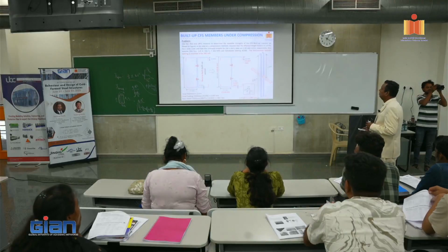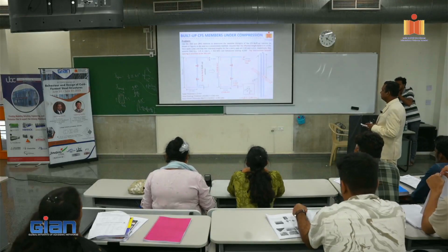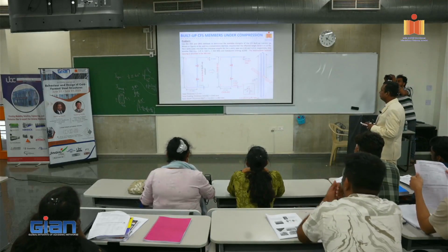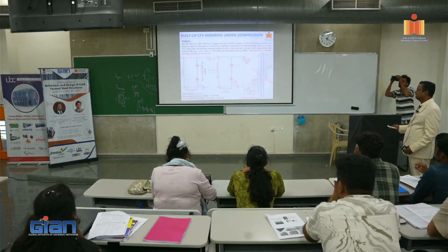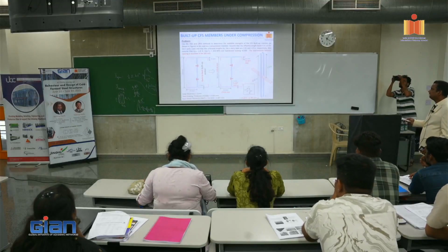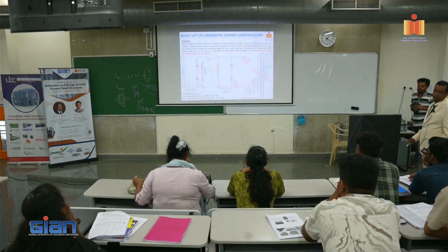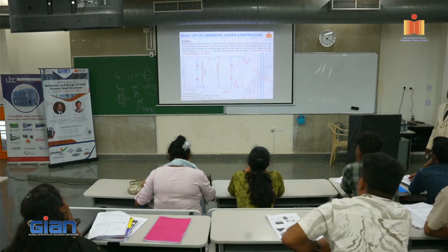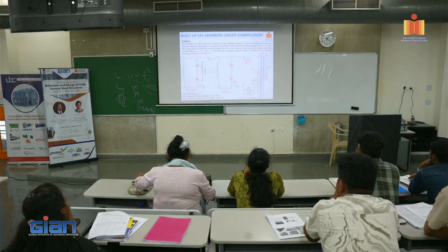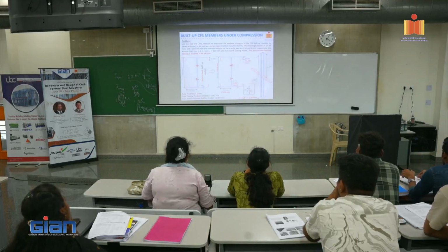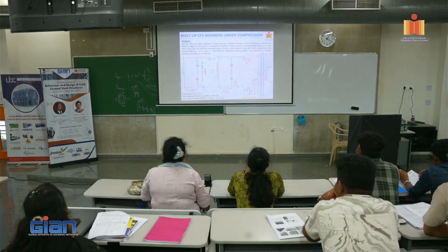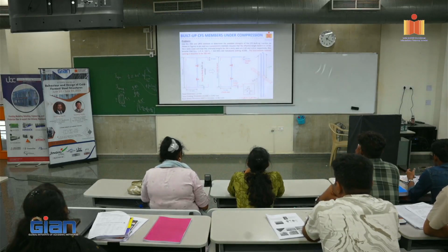Now you transform this section, this 200 becomes 199.96 and this becomes 74.96, the thickness is 1.957, the lip is 14.957, right? Any questions on this one? Okay. So R equal to 1.5 T, so T is 1.957, so you multiply, you get 2.94, that is the radius.